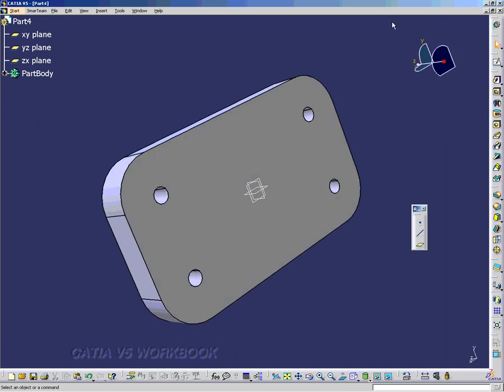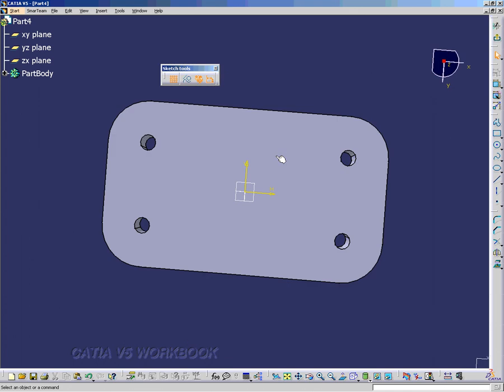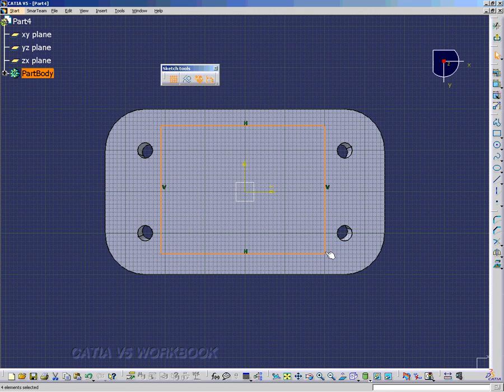Now we'll turn this upside down, and we're going to enter the Sketcher workbench by clicking the bottom surface. We'll just select the rectangle tool and draw a rectangle somewhere near there. Now we'll define the parameters. This top parameter will be 4 inches. The side parameter, we're going to make 3.5 inches. So you just double click on it to redefine it.